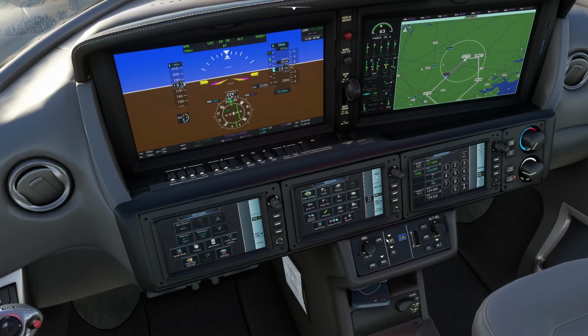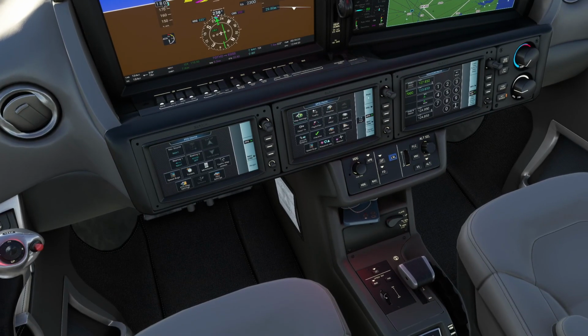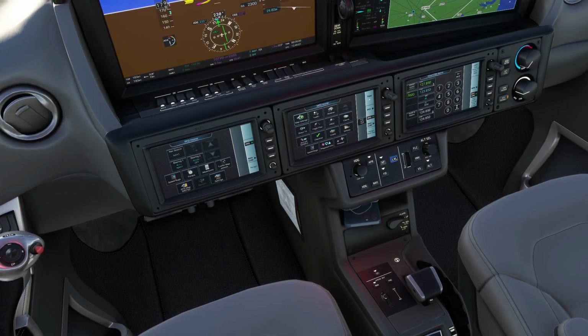So we're already in nav mode, so we're tracking the localizer. If we go and engage approach mode, yeah, so that's the button here. So rather than doing nav mode on its own, which is just our lateral position, it's also going to take notice of the glide slope. So we're going to start slowing down and start dropping the flaps. So let's go for 160 knots.